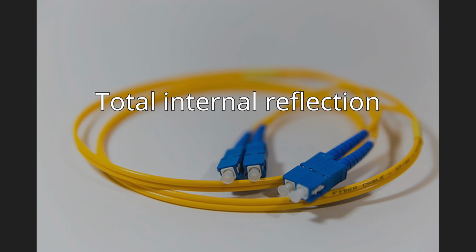Total internal reflection. When light traveling in an optically dense medium hits a boundary at a steep angle larger than the critical angle for the boundary, the light is completely reflected. This is called total internal reflection. This effect is used in optical fibers to confine light in the core. Most modern optical fiber is weakly guiding, meaning that the difference in refractive index between the core and the cladding is very small, typically less than 1%.